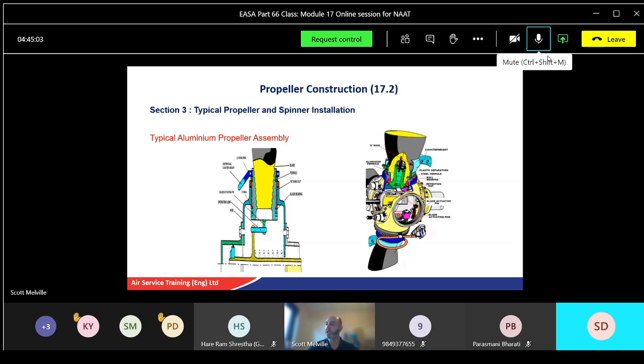And just an exploded diagram of what's all going on. Maybe it'll zoom in there. So there's your little O-ring going round, which stops the grease and oil coming out. There's the green part there, which is the ferrule it's screwed into. And you can see the ball bearing and all the mechanisms that help it move about. Again, that's just an exploded diagram. We'll break these down into more specific components.